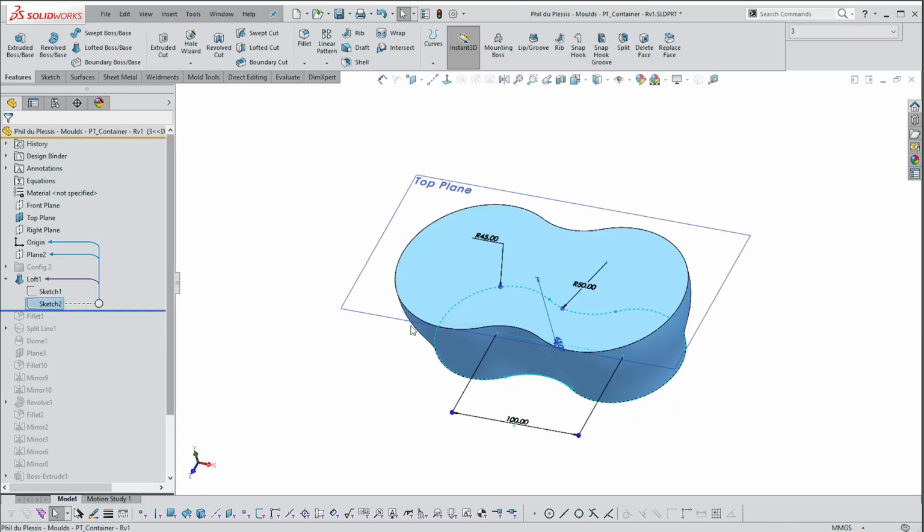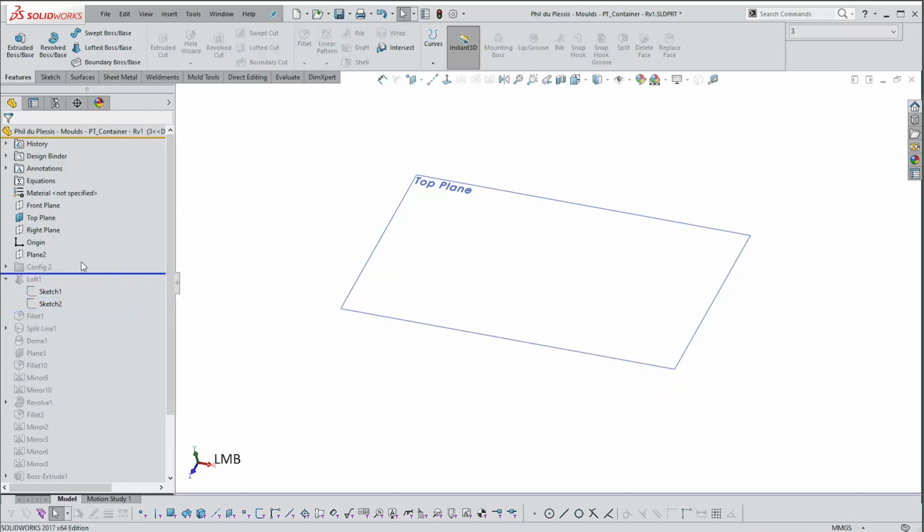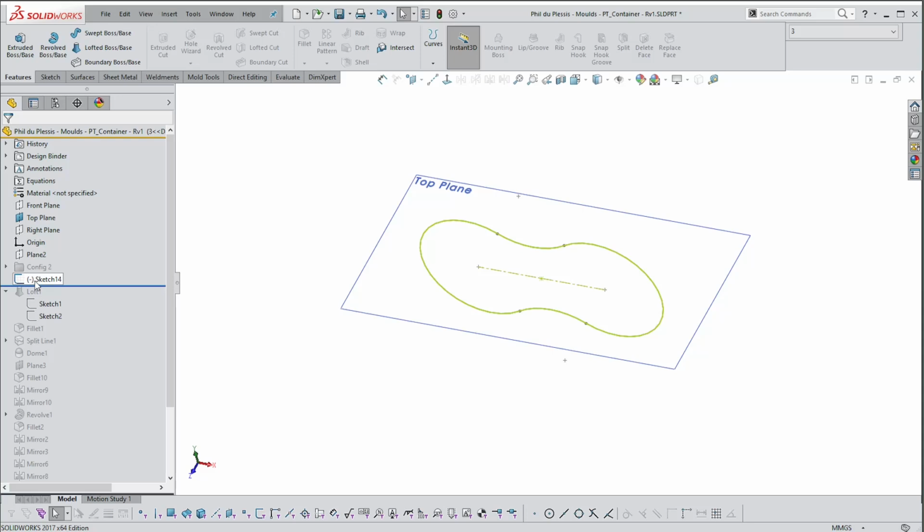So Control C, I'm going to copy this smaller one, Control C, and then just reverse everything so that once you raise this bar up, whatever you do before it gets placed before whatever commands you've got that follow. You'll see how that works. So there we go. That sketch is now ahead of the command from which I've taken it.